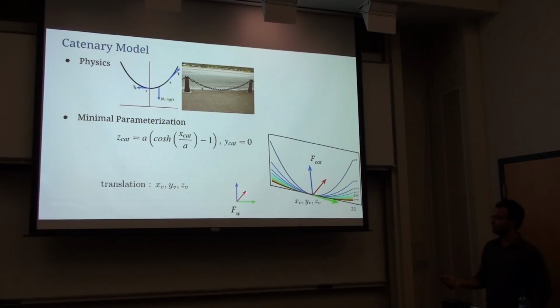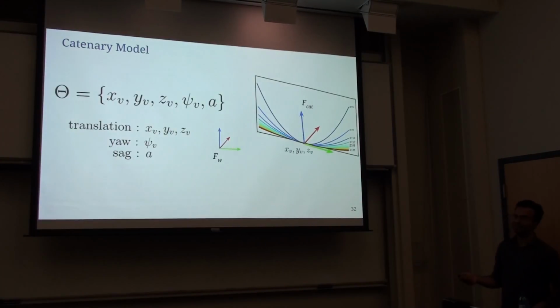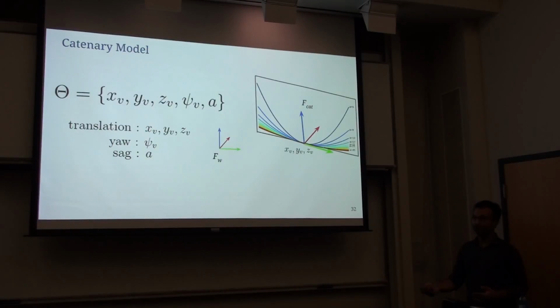And the cool thing here is you don't need to model an SE(3) transform because this thing is in the plane of gravity. So the only thing that you need to do is define your world frame at your takeoff point, and if your drone is sane, it's going to take off anti-parallel to gravity. So you only need to model the yaw, and you also need to model the translation. So these 5 parameters together define our model, and this is the takeaway. There's some model you want to optimize, and there's some equation which can bring these parameters to world coordinates.